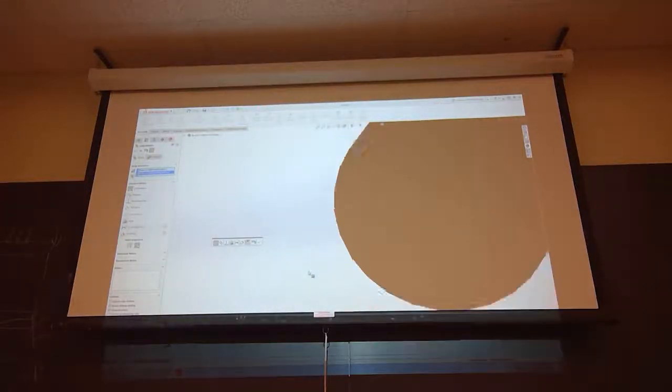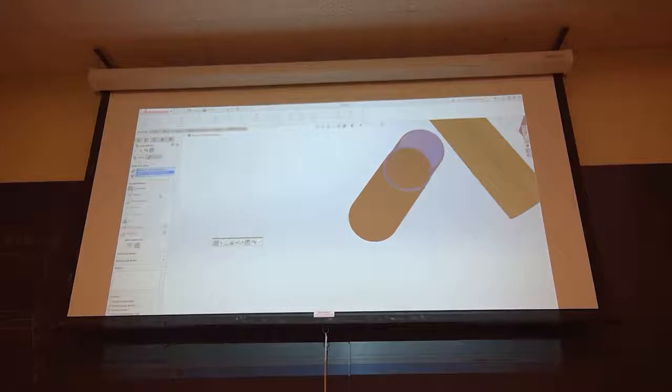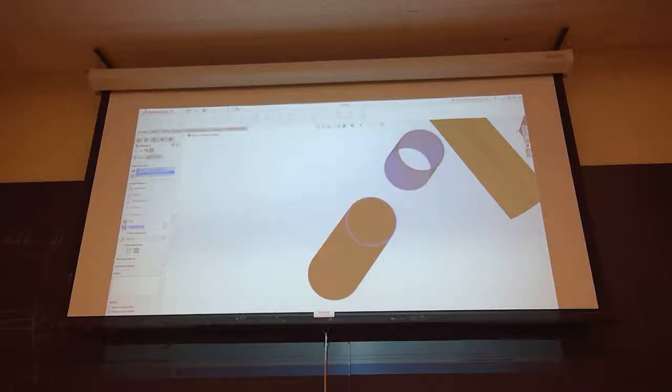Yeah, you should have 2, and then if you look again, it should have gone automatically to coincident, which in most cases is what we want. But again, we want half of our tube to go inside of the main tube, okay? So we're actually gonna hit the distance mate, okay? And it's gonna go back to its original distance. Is everybody here so far?